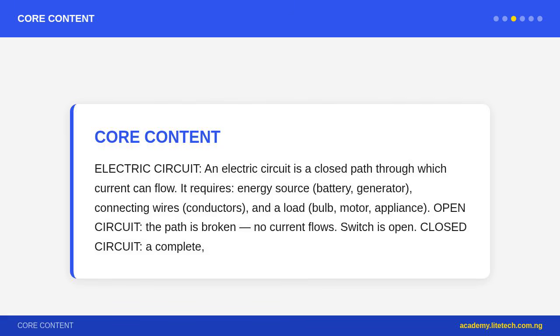Parallel circuit. Components are connected in branches, each branch is an independent path for current. Voltage is the same across each branch. Current is divided among branches, total current equals the sum of branch currents. If one branch fails, others continue to work.